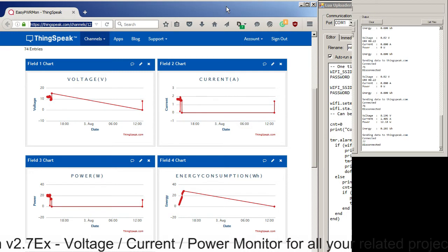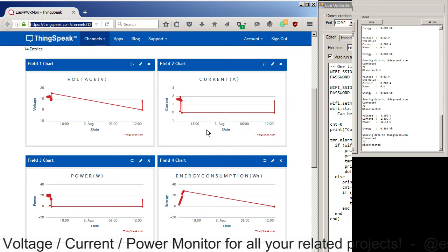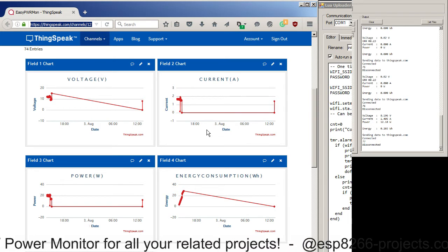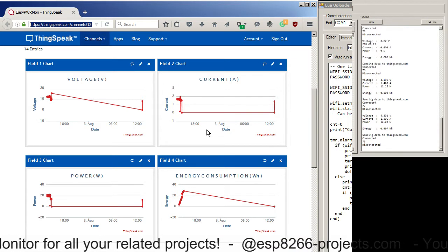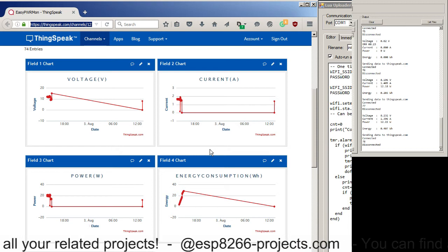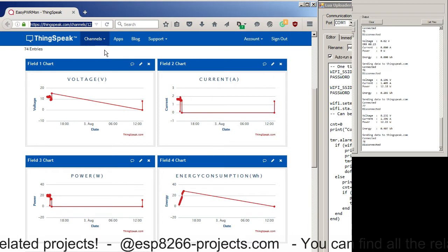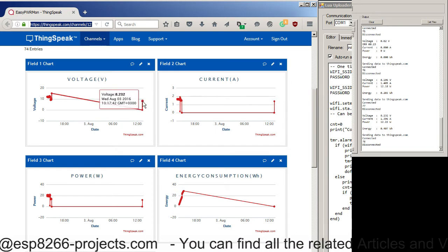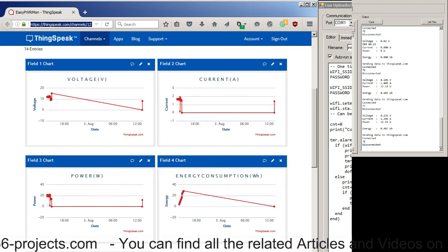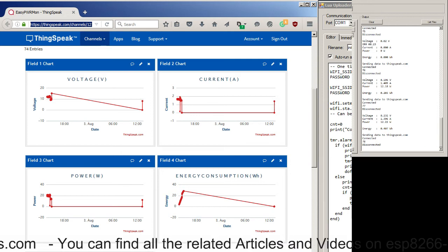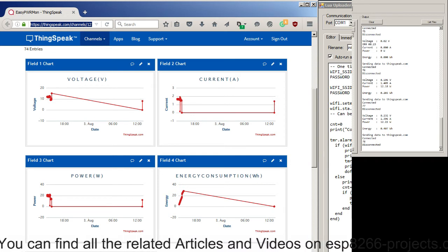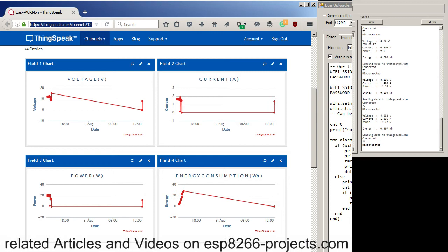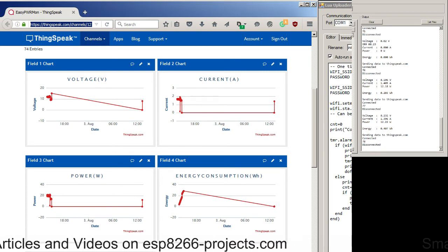Yeah, so this light bulb was giving us from the initial 12 volt about 4 volt dropout voltage. Okay, so now let's try to increase slowly the voltage from the power supply and see what's happening in terms of recorded data on the corresponding graphs. We will see also the variation related with the light bulb. As soon as it becomes warmer, the resistance is changing, and things will change a bit.